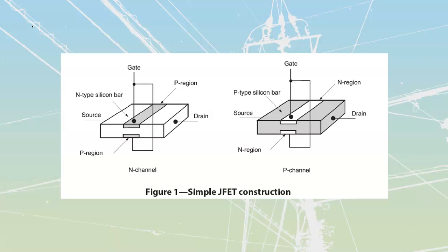The problem with that is that when you've got a device that has got hundreds of thousands, if not millions of transistors inside there, all of that base current adds up. Take a look at your phone, your computer, tablet, anything like that. These all run off of small switches, transistors that are just making decisions in the background, and there's going to be millions of them. If your phone had to use BJTs to do all of that switching, you'd have a battery life of maybe 1 or 2 hours tops before you'd be charging that thing again. So we don't like that. Rather, we want something that's not going to waste current on base current. So we have moved to the field effect transistors.